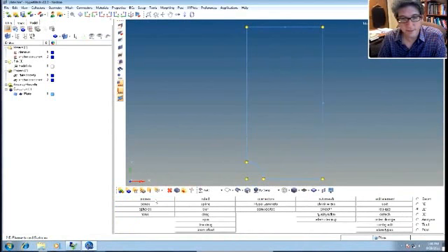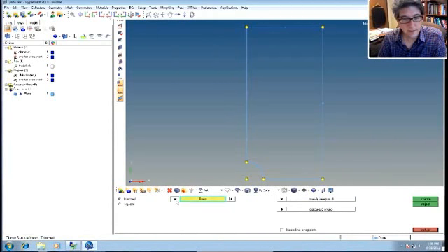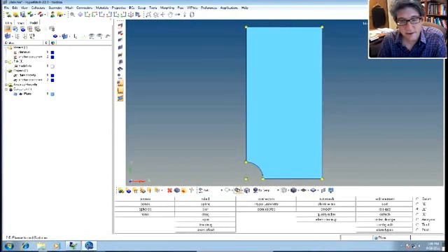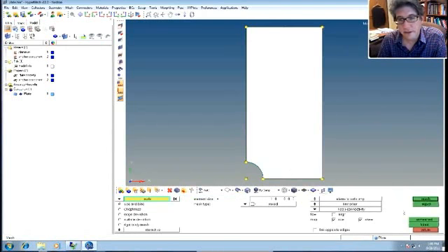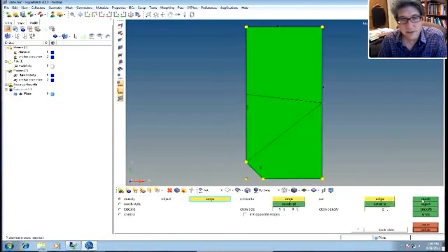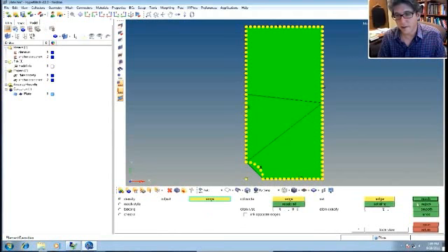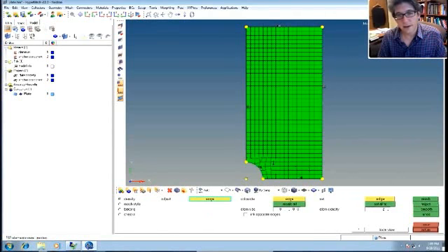So let's go back and pick planes. I think the surface already exists. Yeah, okay, whatever. Pick the lines again. Well, actually, I think that surface exists, right? There's a surface there. So I can directly mesh that surface using auto mesh. And that'll mesh. And you can see here I have the same option, so let's set it to like 0.5. We'll recalculate all the 0.5. And now you can see I probably get a nice, good mesh.